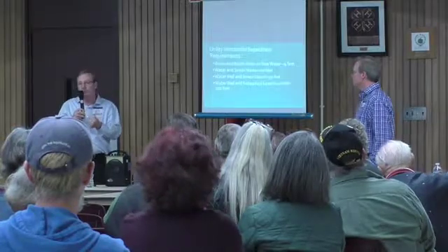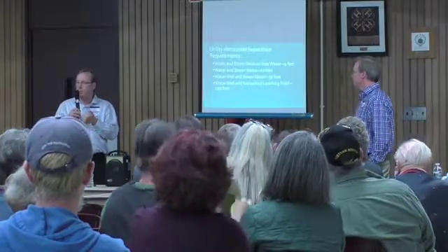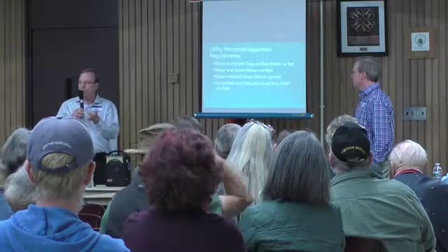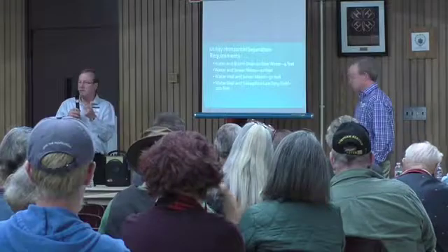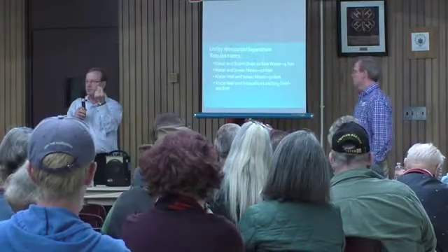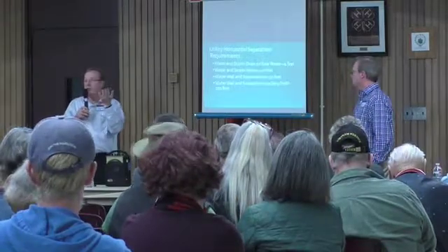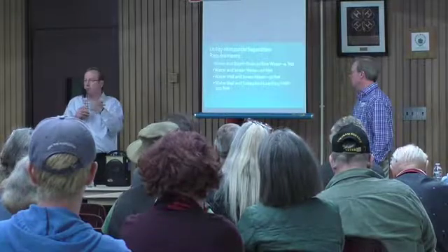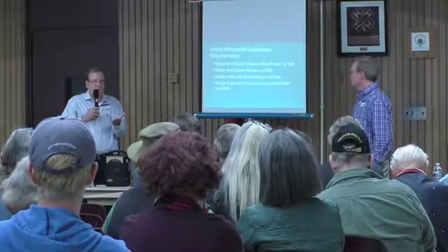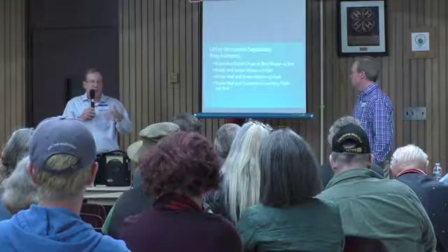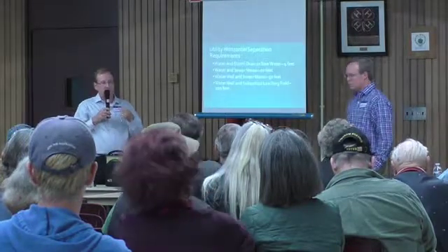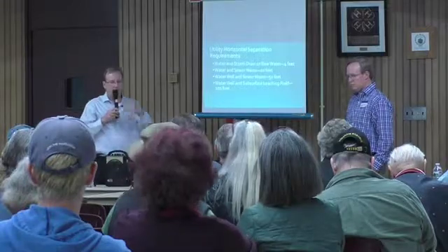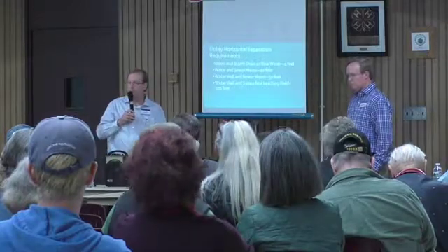Generally, power outages are during the winter, when water usage is down, and we're providing max day storage that relates to summer usage. So you're usually sitting on 3, 4, 5 days worth of storage before you even start to get into your fire protection water. It takes that kind of level of outage to really start to cause you to think about cranking up generators and starting to produce water.